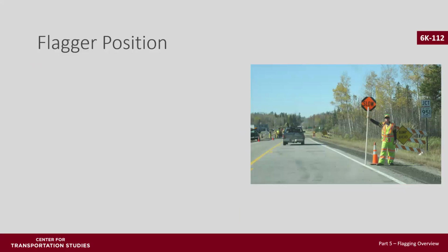The flagger should remain standing and alert at all times. Stand on the shoulder facing traffic. If you have a vehicle at the site, it should be parked at least 2 vehicle lengths behind you and as far over the shoulder as possible. Make note of the location of your flagging station. Make sure you're standing in a highly visible location.